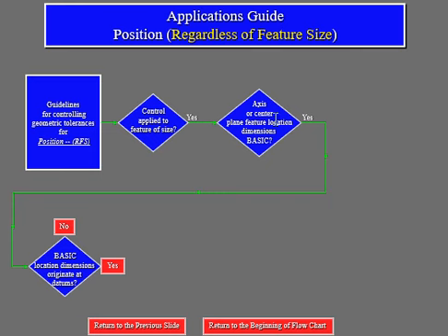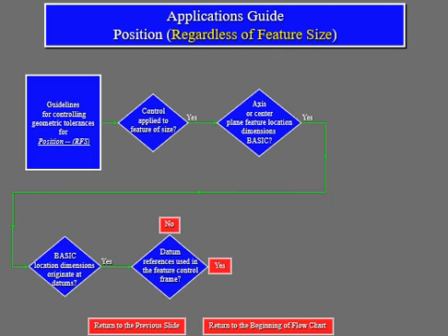So we look at the axis or center plane, the feature location. Just try to remember feature location. Second, we're going to look at the datum location and orientation. Don't forget you're dealing with your position, not the size of your feature. Then we will look at the datum reference. Where do we measure from? Verify from.